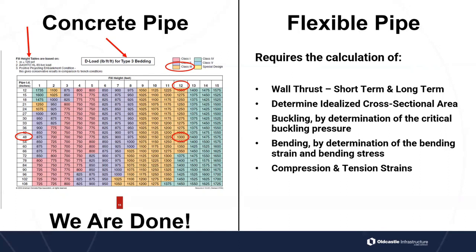It wants to squish a little bit. And so in order to counterbalance that, we need to make sure that our soil and our loading and our compaction and everything we're doing to install that is well within our minimum deflection requirements. Okay. So then the last and probably the most important calculation we have to do as the design engineer is our deflection calculation using the modified Iowa formula.